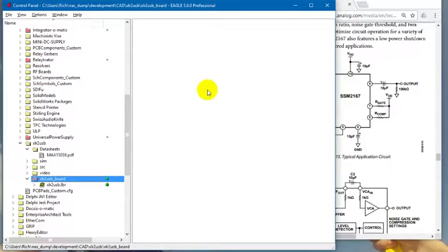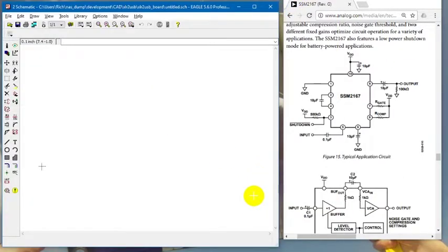If you are importing multiple libraries, like the Eagle built-in libraries or something like that, those must be selected as well. But like I said, I like to use everything from a single base library for that project, and then we'll just copy stuff in. So let's begin to do that. In order to add something from the library, you can either use this icon here, which I know the look of the modern Eagle 8.5, I think we're on right now, is a little different.